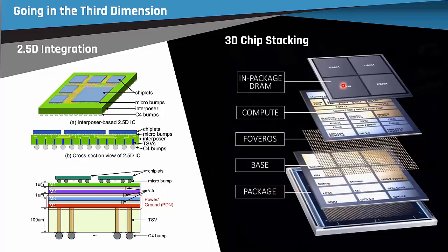Intel showed last year this process called Foveros, which is true 3D stacking, where you actually put one die on top of another, and you connect them again through some sort of, here, this whole plane is just for connections between chips. There are all kinds of issues here with heat dissipation and all kinds of stuff, but it really gets you very, very good and amazing connections. And that's called 3D stacking. And TSMC, I think they call it 3D IC or something. They also sell a process that does this, but not many companies are doing it yet. But for sure, in our really near generations, everybody's going to be doing this, or at least whoever wants to get really strong and complex systems.